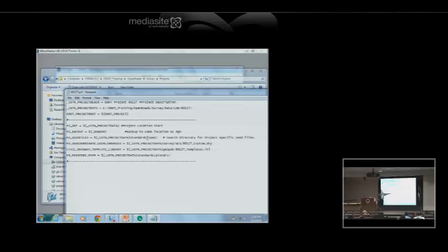We talk about the geocoordinate user library. I mentioned a geographic coordinate system can be customized for that grid-to-ground conversion. That customization happens in a .bty file, which will be unique for every project. So one of the things defined at the project level is a custom geographic coordinate system for grid-to-ground conversion.